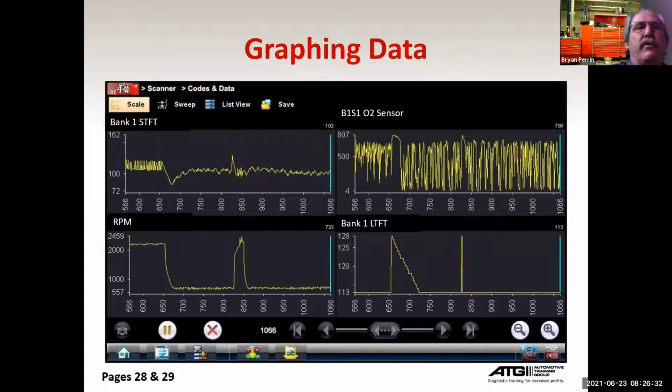And of course, I can go down the rabbit hole. I can get a lab scope on it, and maybe I might see something, but again, I might not. I could disconnect everything to an ohm meter, but that's not really going to tell me anything. I could pull the injectors and do a flow test with the injectors on a bench if I had one, which I don't.